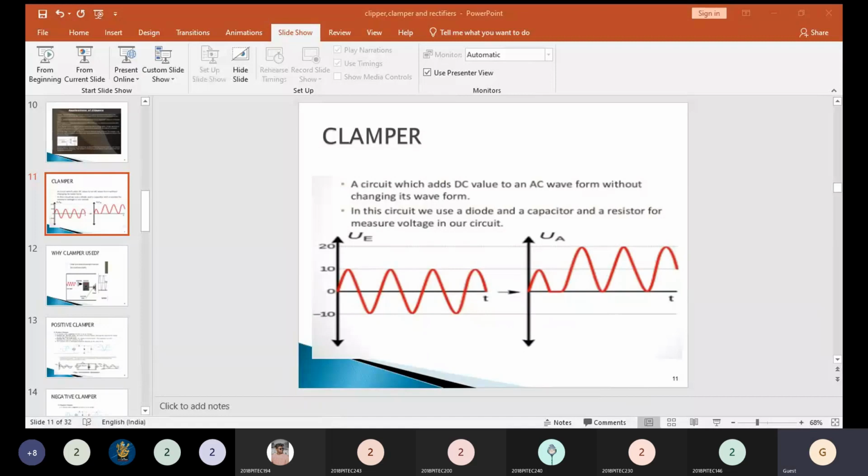So parallelly we are getting a positive half cycle in the first half cycle, and in the negative half cycle we are also getting a positive cycle. So what happened now? We are getting double the value of the input signal as the output. But in the half wave rectifier, F out is equal to only F in. Here two diodes are used, so the output is equal to twice the frequency of the input signal F in.